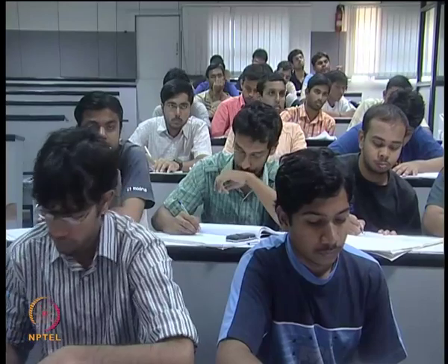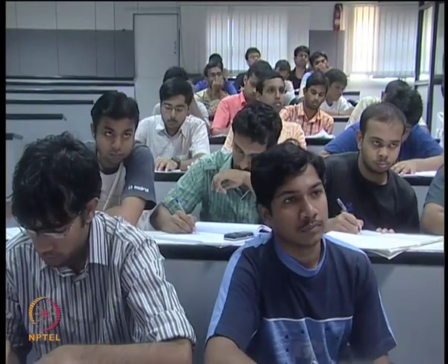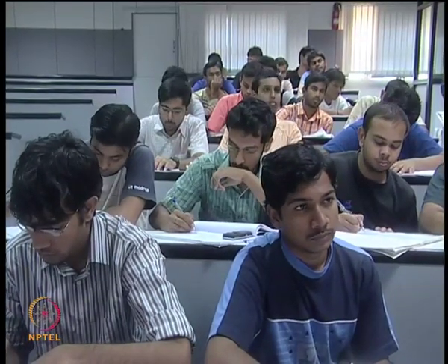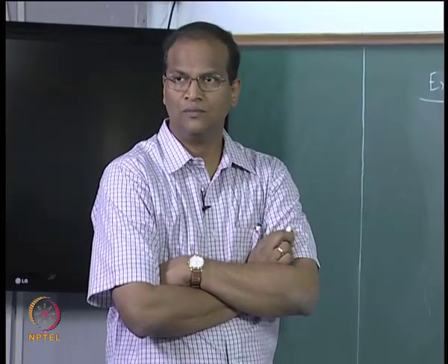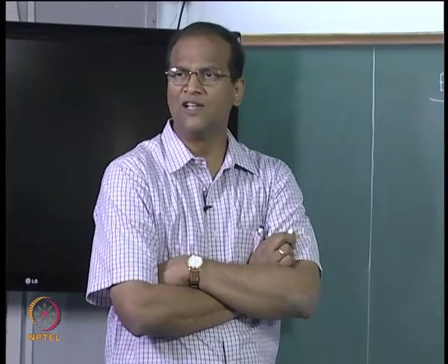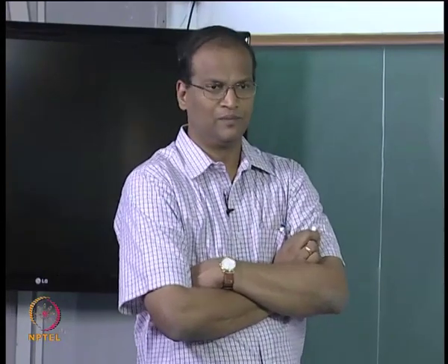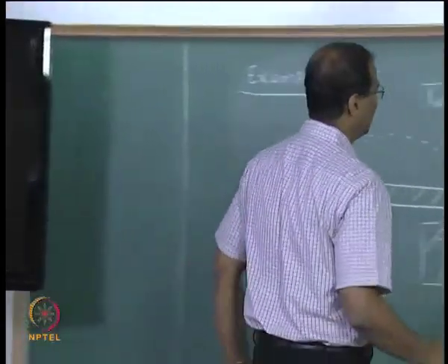Because the emissivity of the surroundings is considered to be 1. So it is a waste of time to get F21, F22 and all that. Whenever you have surroundings like this, do not waste time in calculating those view factors. Now therefore J2 is straight away